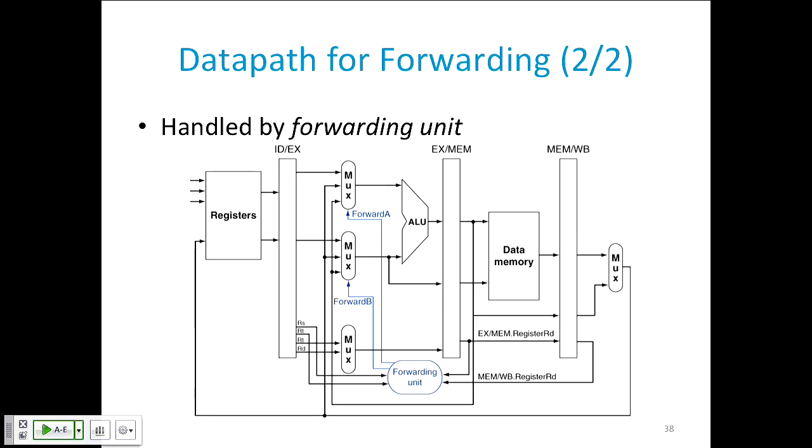Remember that we captured the instruction register and shifted it down the pipeline. And one of the things we captured is which register I am going to write, so that when I got to the end of the pipeline, I would write the correct register. That information tells you which register is going to be updated by that instruction. You compare that with your source operands, the registers you're going to read. If there's a match, you know that I need that value that's still in the pipeline, right? So you're comparing all these register numbers here with my source register numbers here.